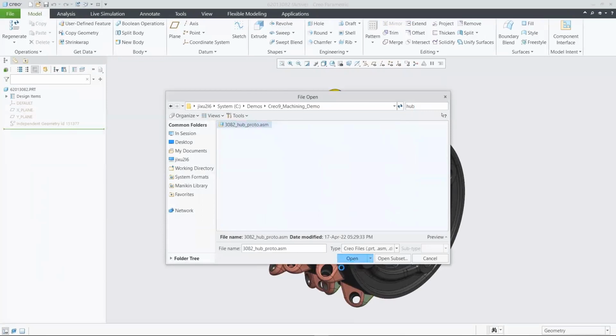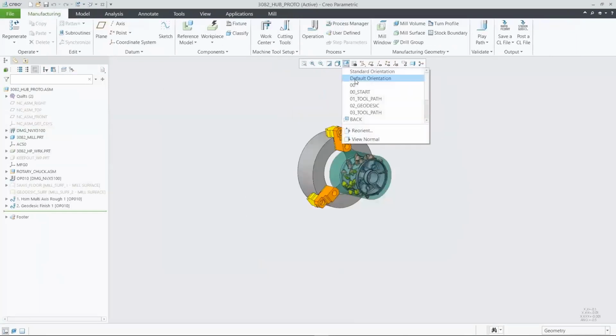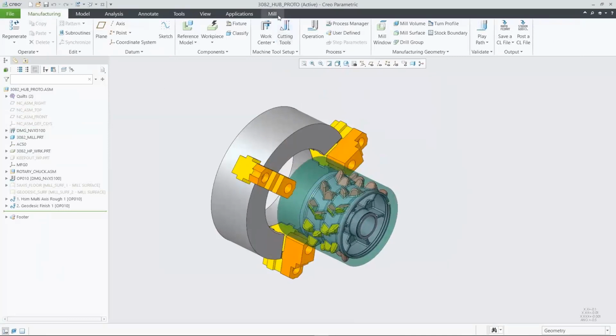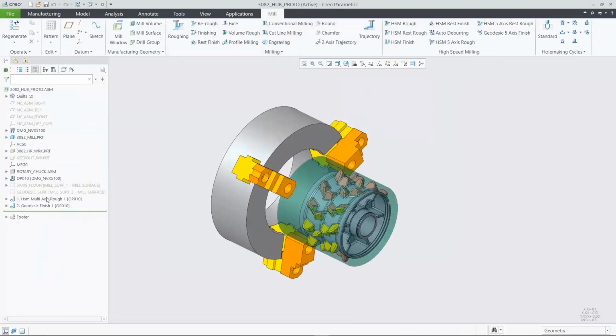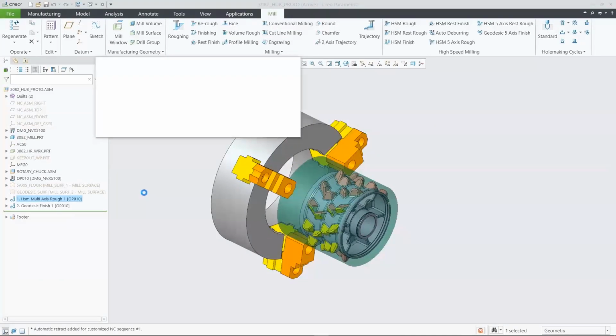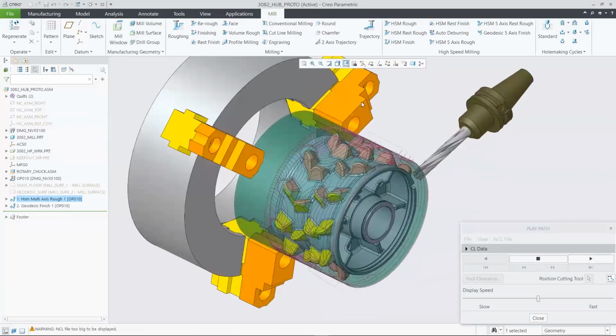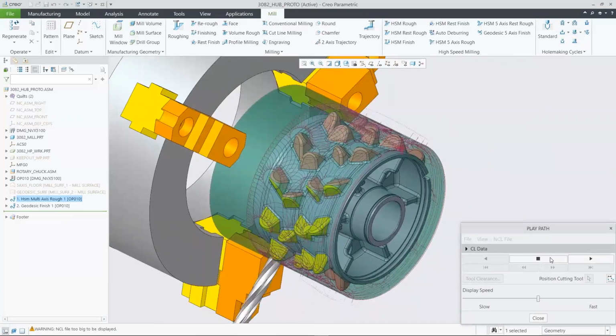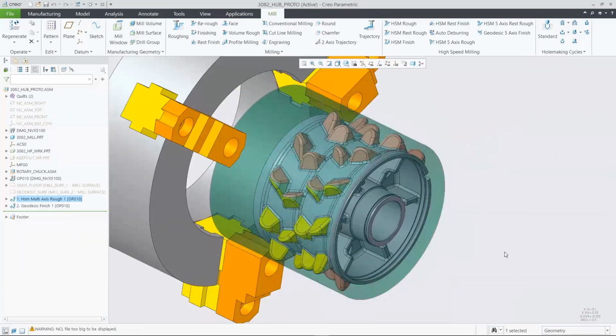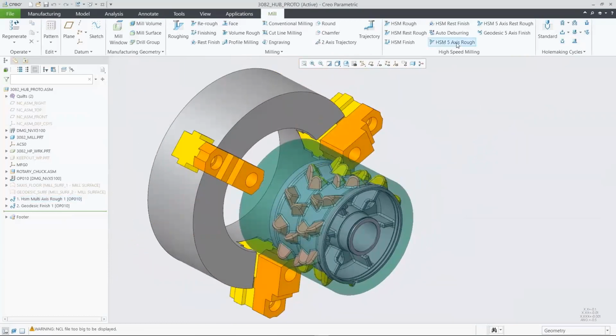Check that out. Here, we're going to check out a few of our tool paths. In this case, let's look at a multi-axis roughing tool path. So this is what you want in a part like this, right? You really don't want to spend a ton of time treating this like a 3-axis mill, taking hours and hours to try to set that up. So you just want to machine all of that. And because it's a multi-axis tool path, it'll rotate the tool for you automatically. It gives you a very efficient tool path. And that was something that was introduced back in Creo 8, but now with Creo 9, we have a new one.